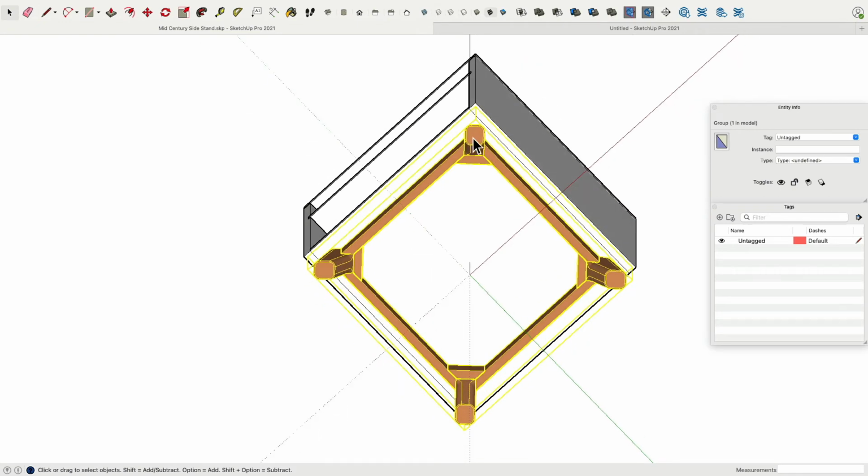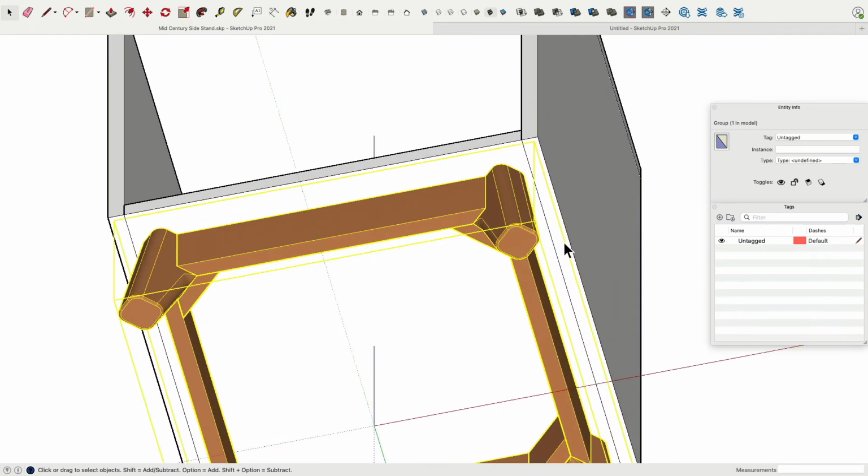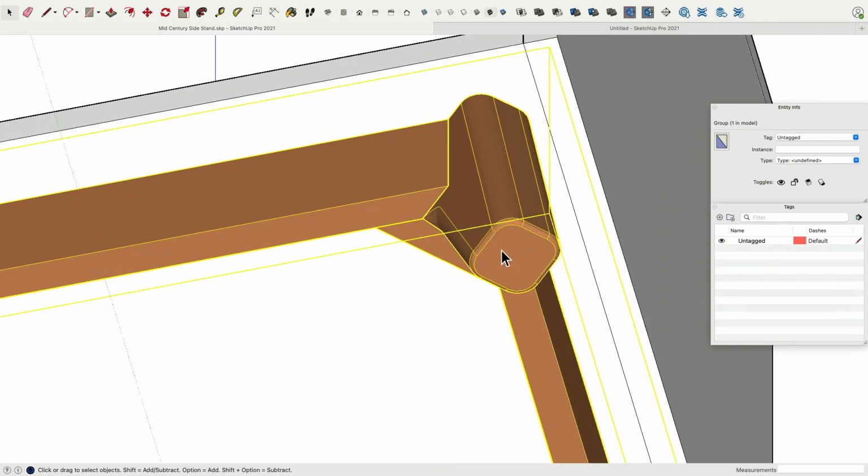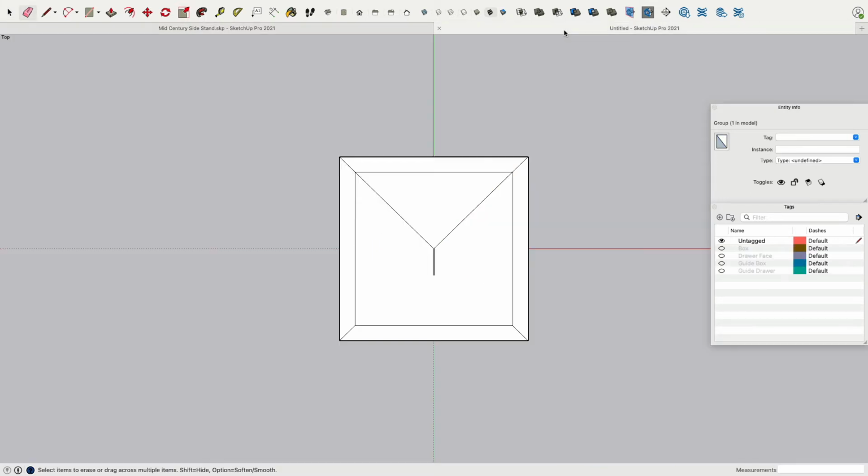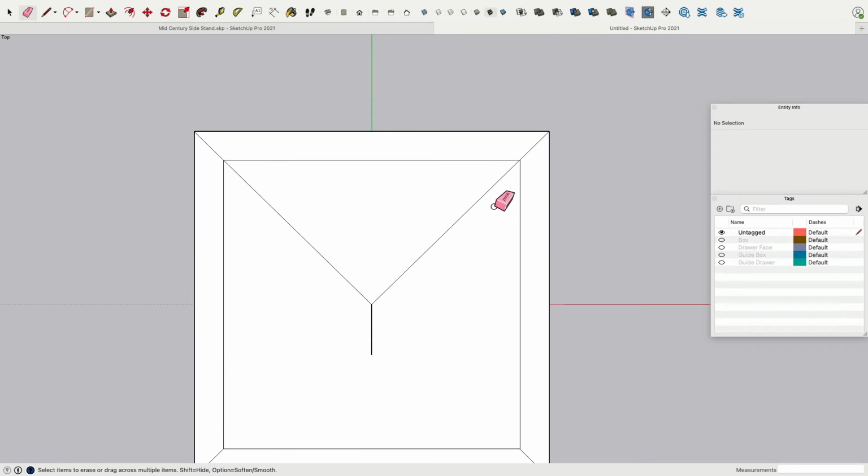You see here these legs, they are 45 degree and they're rotated. And the thickness is actually, we set them to 34 millimeters. Okay, so when this is at the center, I can click and drag. So 34 divided by 2 is 17. 17, there.